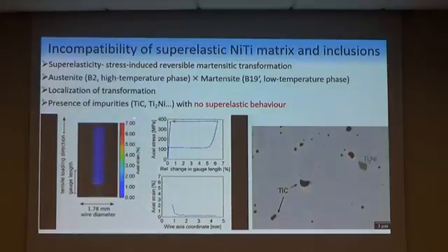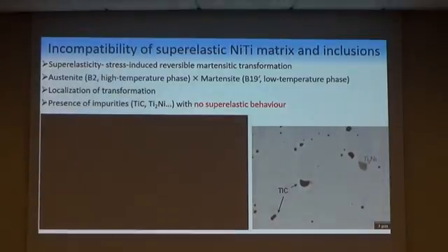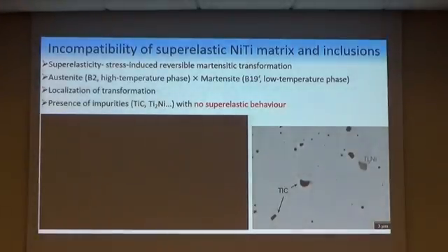So almost 7% strain is in the martensite part of the wire. On the other hand, only about 1% strain is in the austenite part of the wire in this plateau region. So only the ratio between austenite and martensite content is changed in this area.